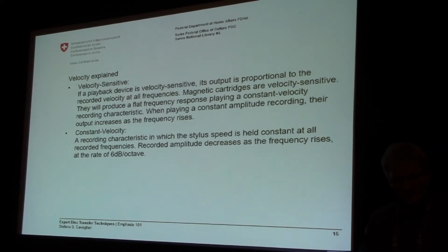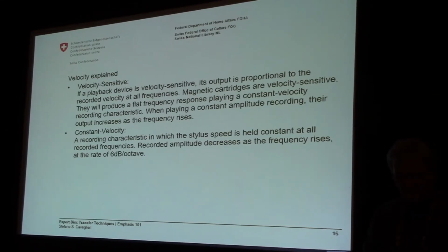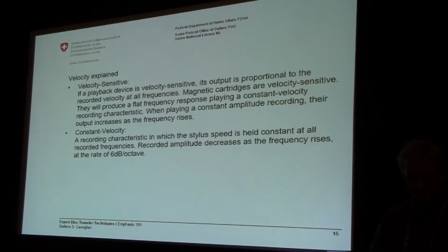Otherwise, the output increases as the frequency rises. By constant velocity, what we mean is a recording characteristic in which the stylus speed is held constant at all recorded frequencies, which means that the recorded amplitude decreases as frequency rises at the rate of 6 dB per octave.